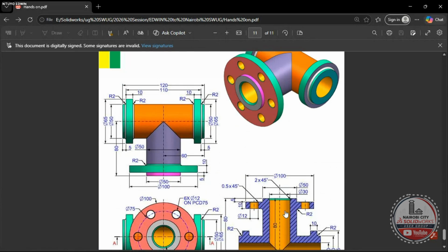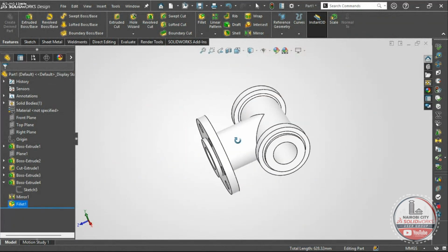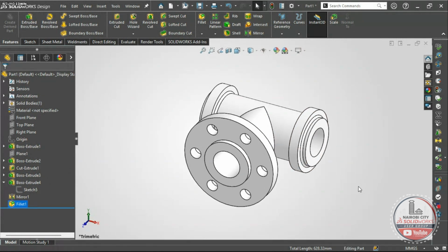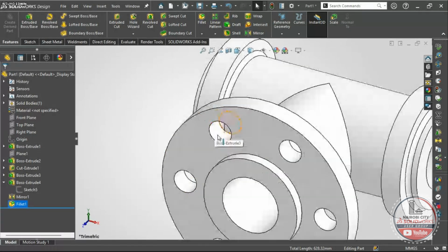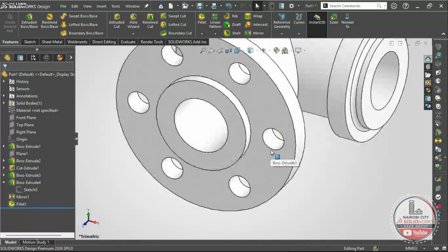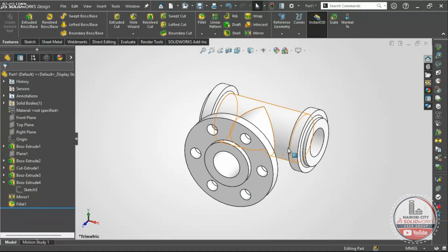Another thing we're about to add, because this is a flange. For example, this is a plastic flange that is going to be used. However, in my point of view, I've never seen a plastic flange used with boards, because this face is going to be mounted with a gasket, and then you add another flange for connectivity. So this is automatically metallic, so I need to come to edit material, not specified, right click, edit material.